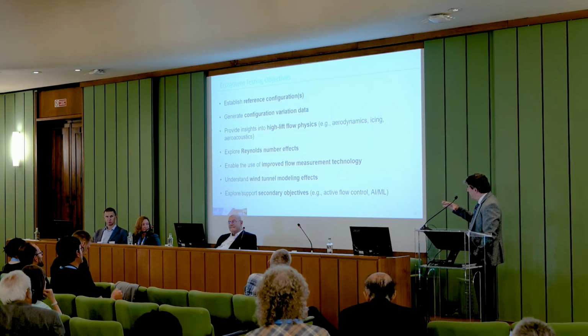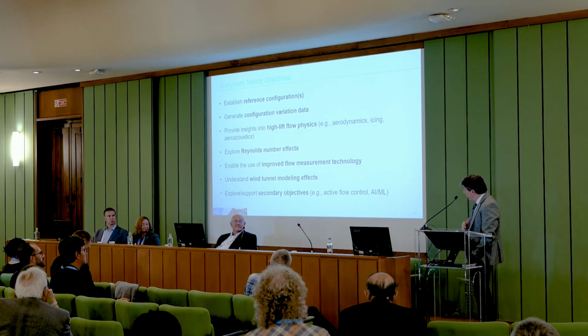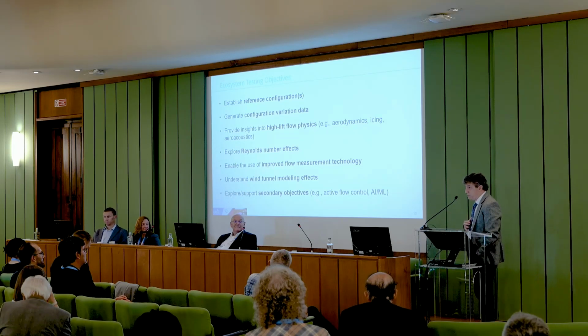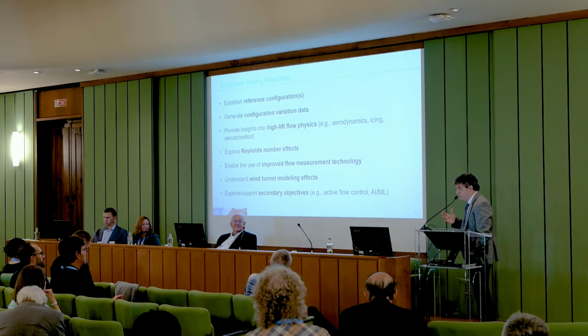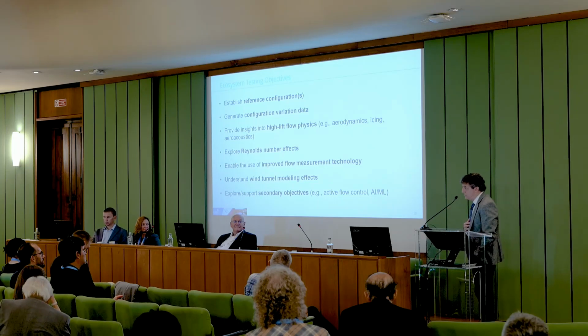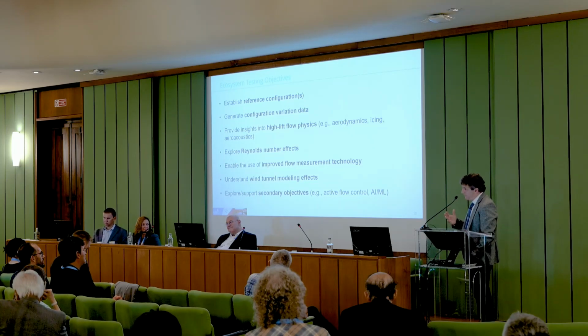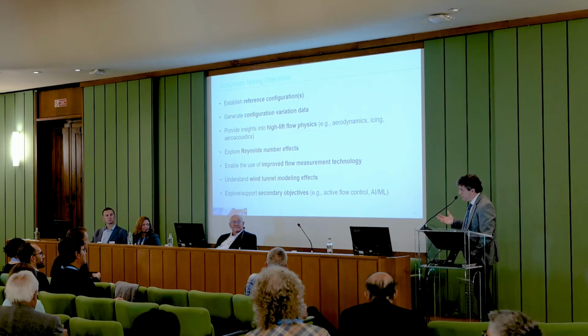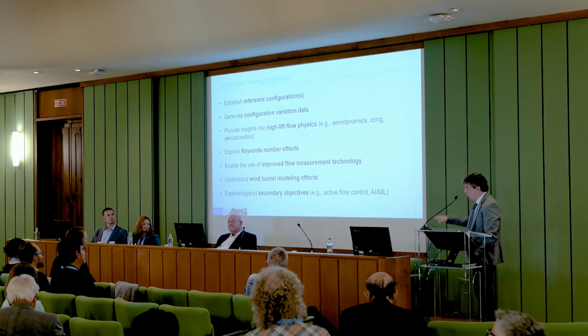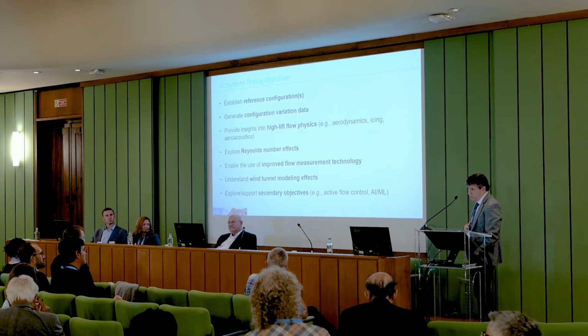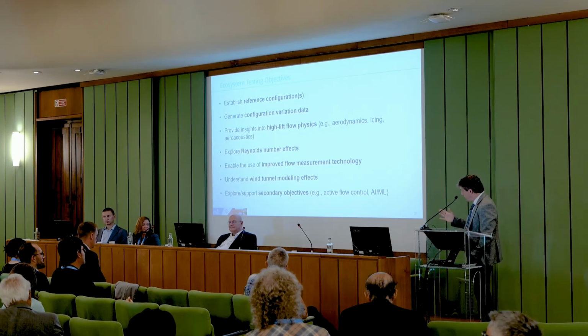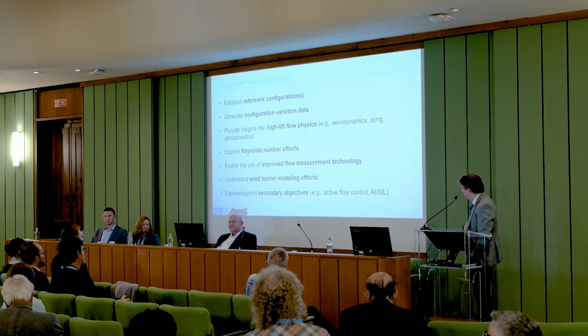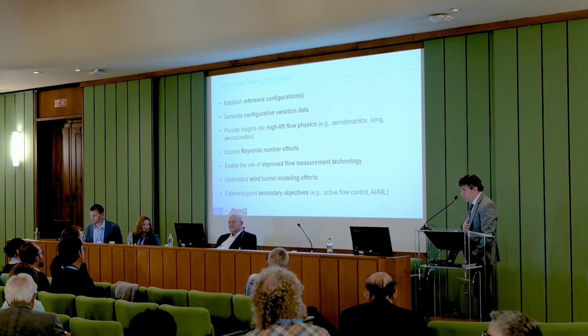Now within the industrial elements, we want to study Reynolds number. So clearly, Boeing is very interested in understanding what a high-lift system does at flight scale. So getting up to the highest Reynolds numbers possible is really a key objective. And so we have multiple partners now that can run at a range of Reynolds numbers. So we're getting data across a range of Reynolds numbers. We'll see a little bit more about that in a minute. Again, this enables the use of improved flow measurement technology.